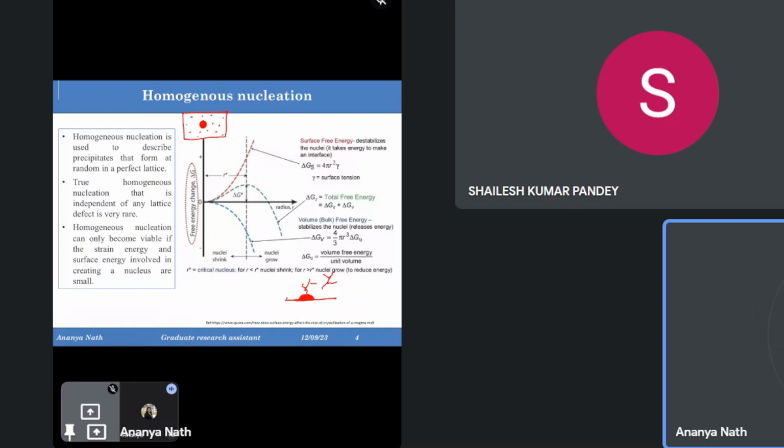If the nucleus achieves a certain size, it will grow and form the grain. It will be called a nucleus only once it gets that diameter or size. Here the assumption is that the nucleus is spherical, and making a spherical nucleus out of nowhere is also very tough. Also there was one thing, R star. Unless the thing reaches the size of R star, it will not be called a nucleus. It will be called an embryo.